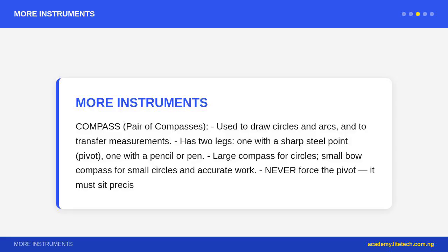Store compass and dividers in a case, never throw them loosely in a bag. 2. Sharpen pencils regularly, always before starting a drawing. 3. Never scratch the drawing board surface. 4. Keep T-square and set squares clean, fingerprints and oil smudge drawings. 5. Oil the adjustable joint of the compass occasionally to prevent stiffness.